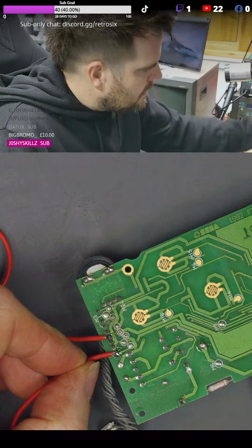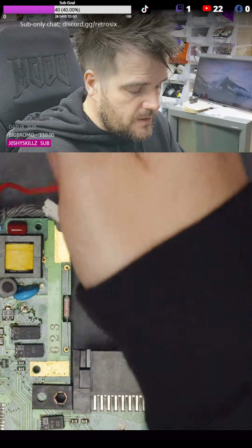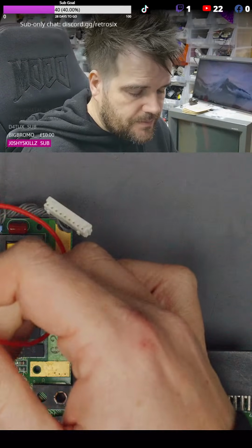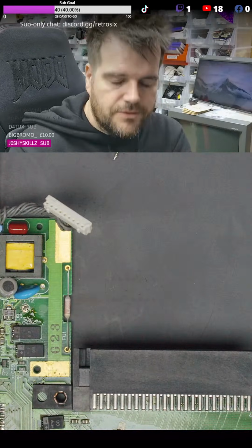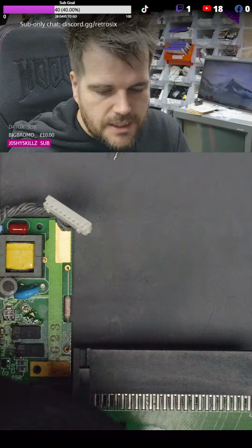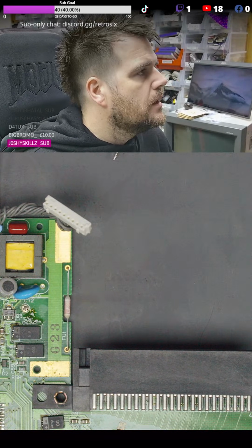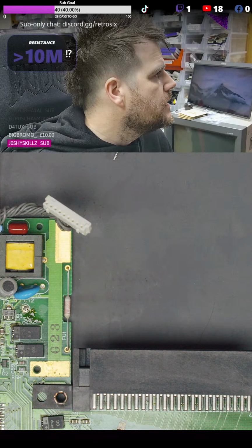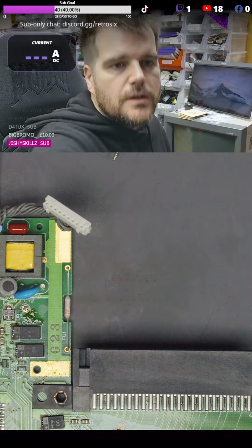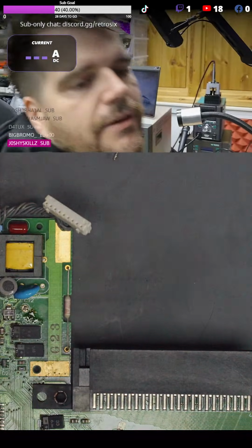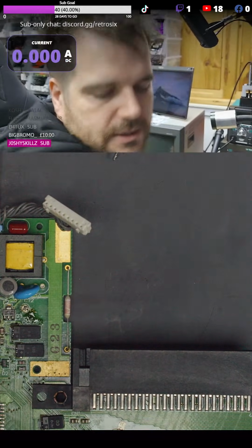So now I'm just going to power this board up through the bench. Ground can be ground, which is normal, and 5 volts can be 5 volts. To show you the actual current draw, I should be able to bring up the meter, go to current, put the probe in the right connector place, like so.